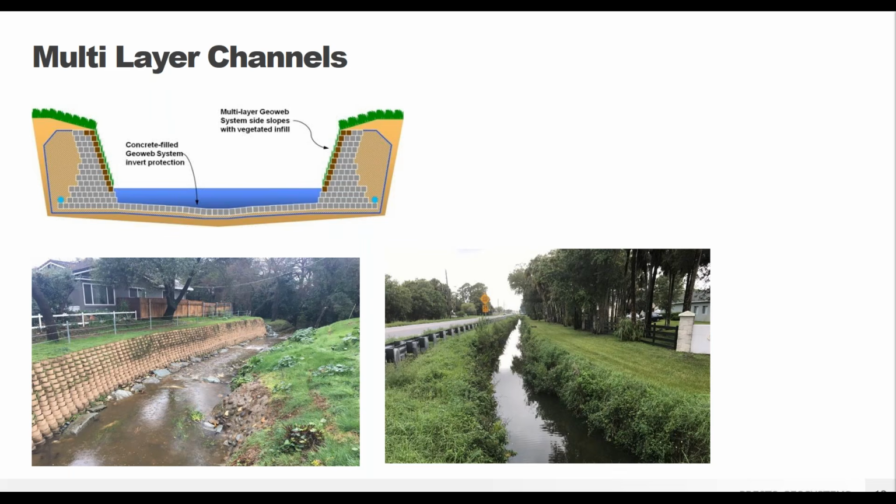GEOWEB retaining walls can withstand the same velocities and shear stresses as that single layer system, and they're still flexible enough to handle curves and changes in grade. So you're not limited by the functionality of the GEOWEB system if you do need to go through this multi-layer method. It is just a little bit more construction intensive.